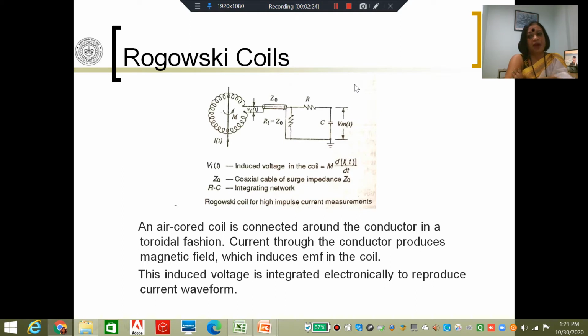And therefore, we try to look at alternative techniques, which may be electrical or non-electrical, so that we can estimate the PD that is taking place and decide on what course of action to be taken. The first technique that we will talk about is the Rogowski coil. In the Rogowski coil, let us imagine we have a current carrying conductor. This current carrying conductor may or may not carry any current. Imagine you have a balanced circuit condition, and under balanced circuit condition, no current flows through the current carrying conductor, or even if there is current, it is a steady current that is flowing through the conductor.